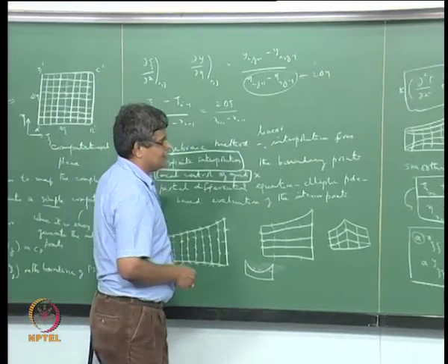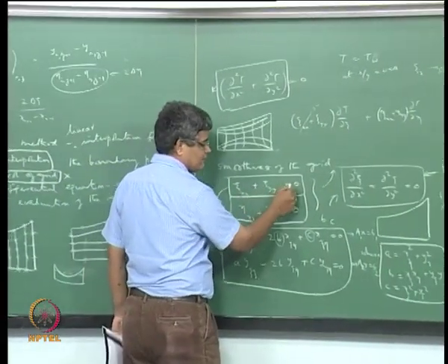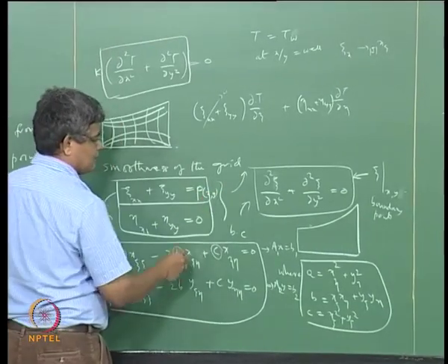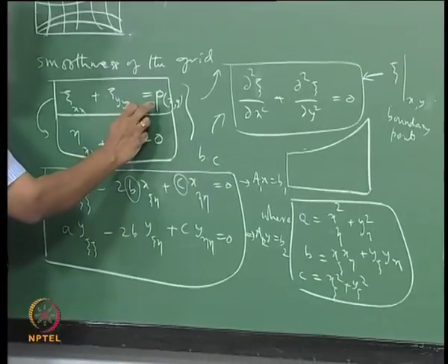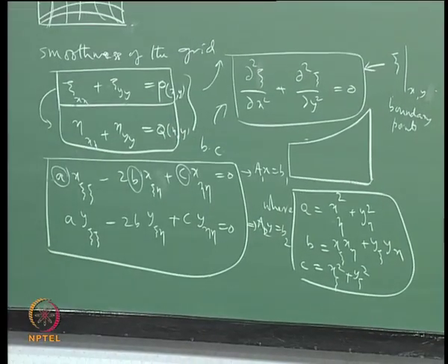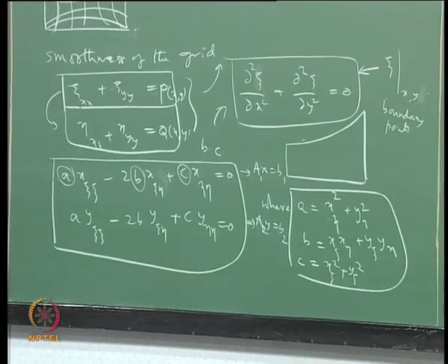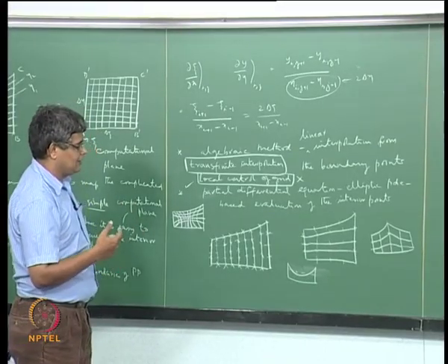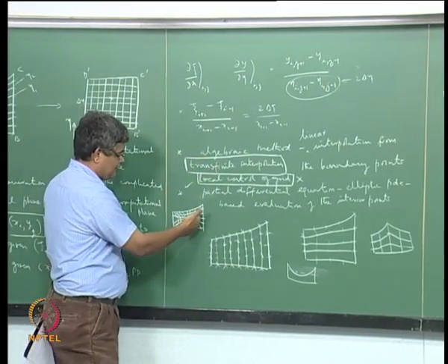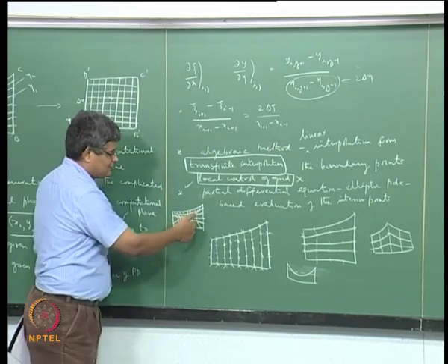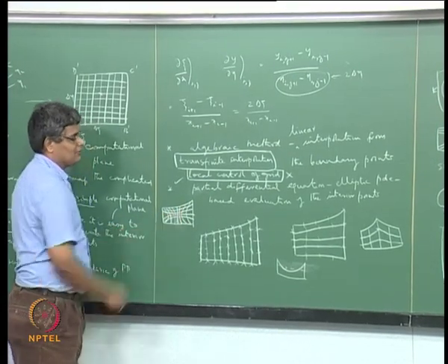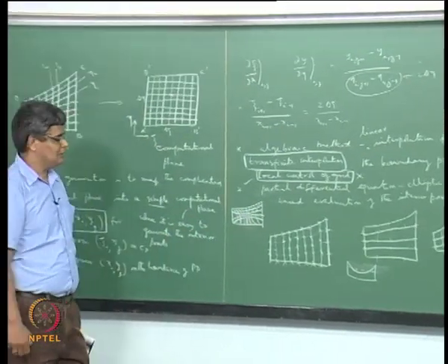And in such a case we won't be solving just these Laplace equations, but we can solve with the Poisson equation, which will have some source points put at different locations, the strength and location of which are for our consideration. Making use of the strength and location, we would like to make these grid lines, constant eta and constant psi lines, get attracted towards this in order to make local grid refinement possible.